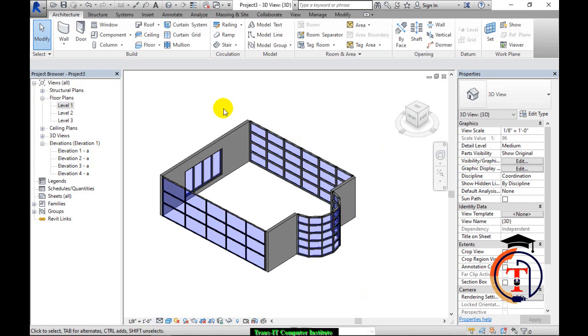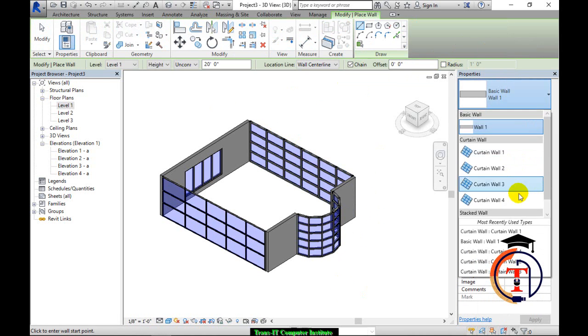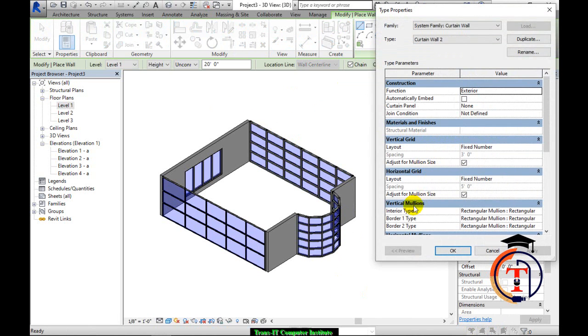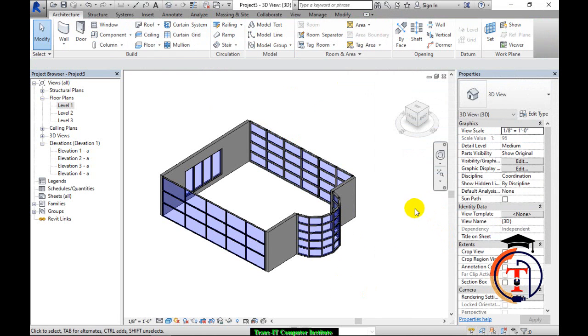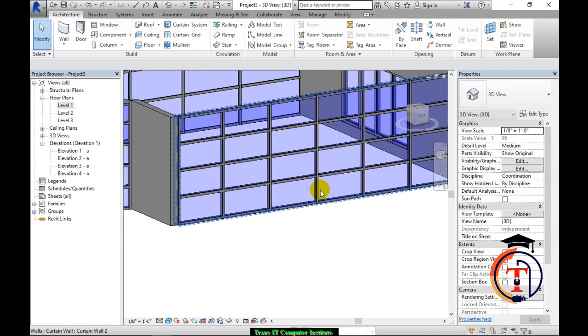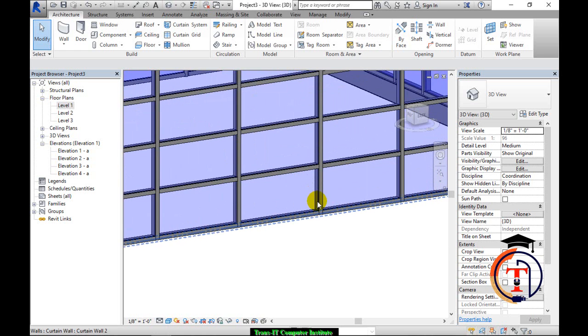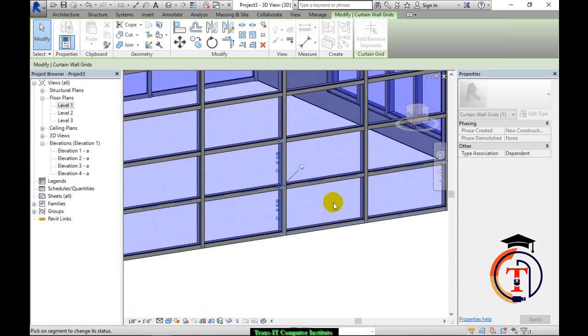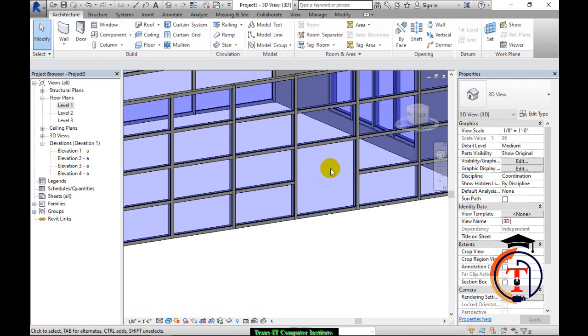What we learned today is: having a wall, converting it to a curtain wall, making it a duplicate, then if you convert it to the duplicate wall, how to apply the horizontal grid, vertical grid, Mullions and everything. Okay, now last module, last tricks I want to share with you. If I want to show the door over here, similarly if I want to remove this, I select Tab. Okay, Edit Segment, I remove these segments. Now this panel I want to convert into a door panel.